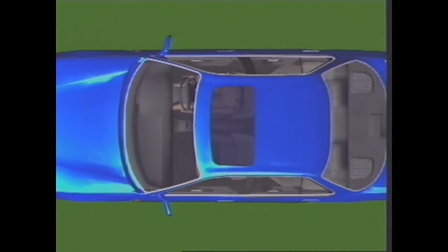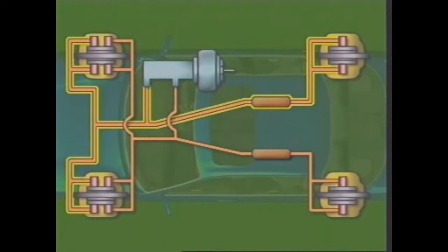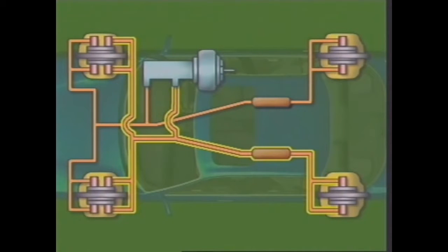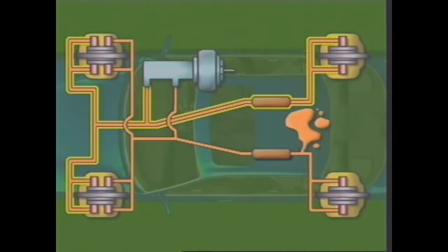An alternative arrangement for front-engine rear-wheel drive vehicles is an L-split. The front disc brake units have 4 piston calipers. 2 of the pistons on each front unit connect to the right-hand rear, and the other 2 pistons of each unit connect to the left-hand rear. As with the X-split, if there is failure of either half of the system, it still leaves 50% braking capability.